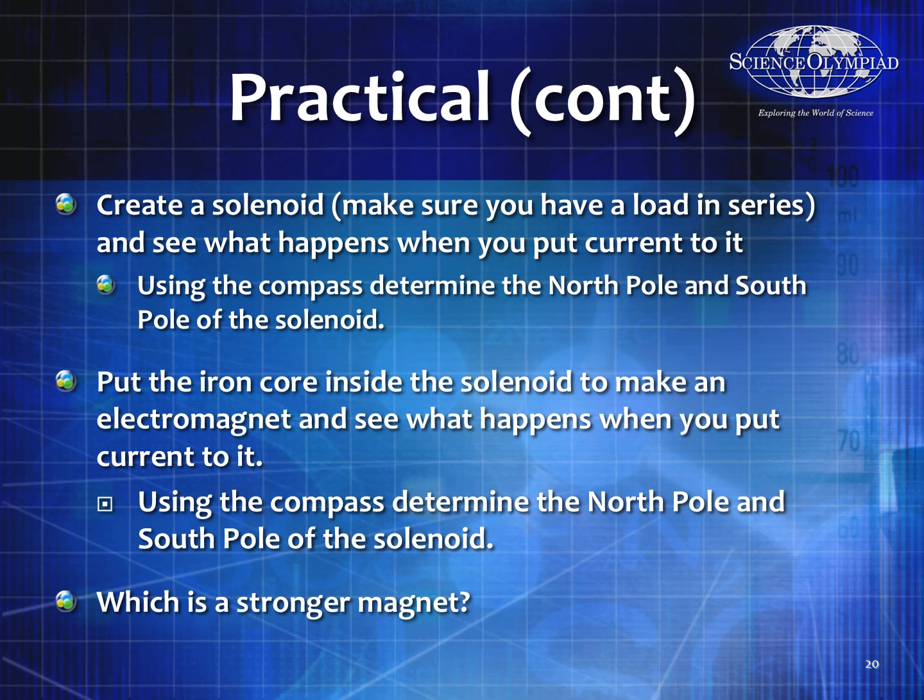Then what I usually like to do is wrap it around an iron core, usually a big bolt, and then I compare how strong that magnetic field is with the iron bolt in it and the iron bolt outside. The iron bolt within it is always a stronger magnet.